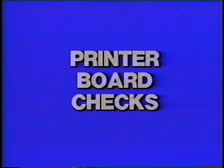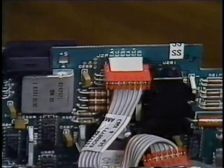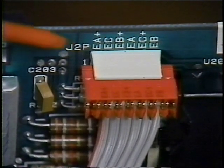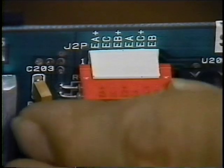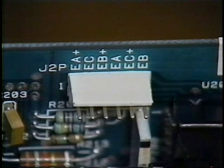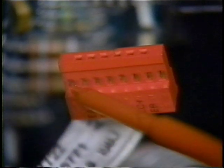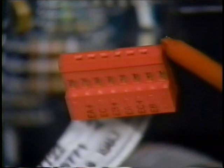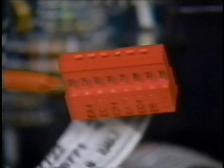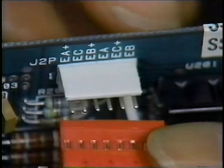In this section, we will discuss some of the diagnostic checks done on the printer board. First, let's locate the connectors on the printer board. This is the transport motor connector J2P. Note that there are 6 pins on the printer board, but there are 8 pins in the connector. The pin on each end of the connector is blocked so that the connector cannot be plugged in wrong. The connector plugs onto the board with the printing on the connector facing up.